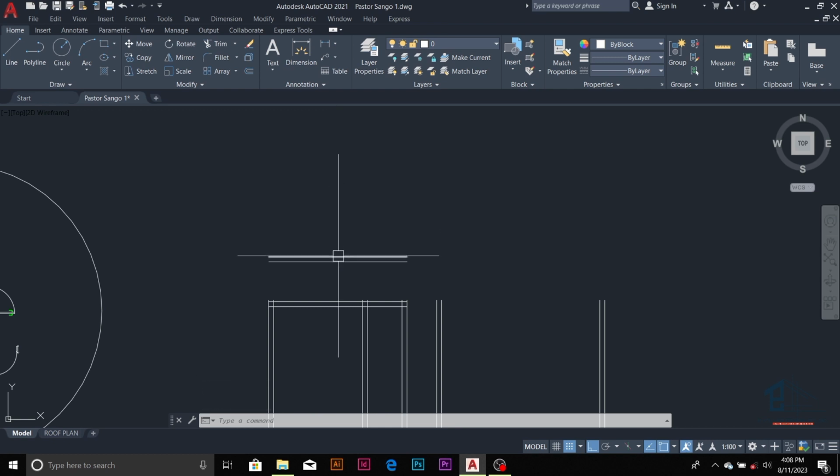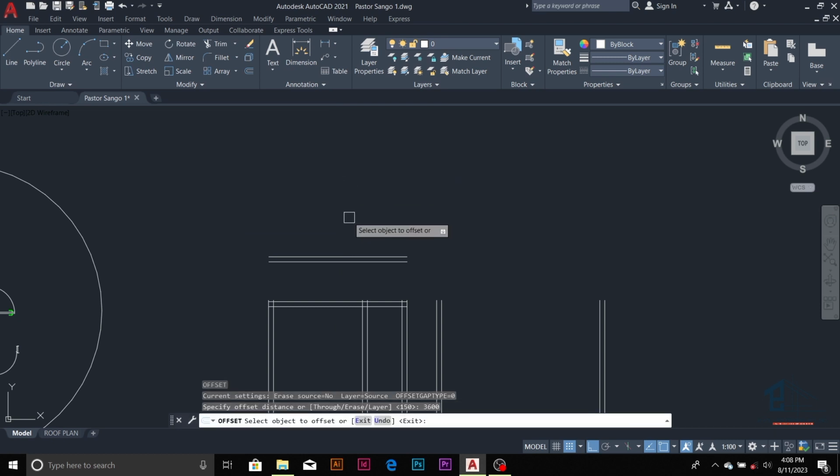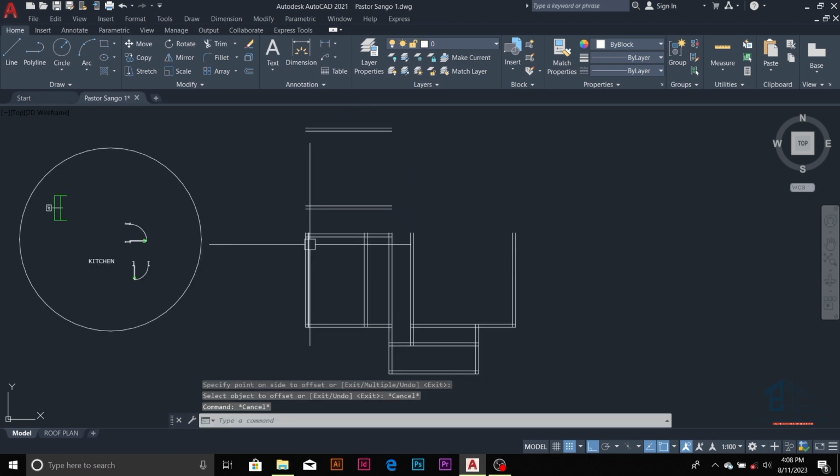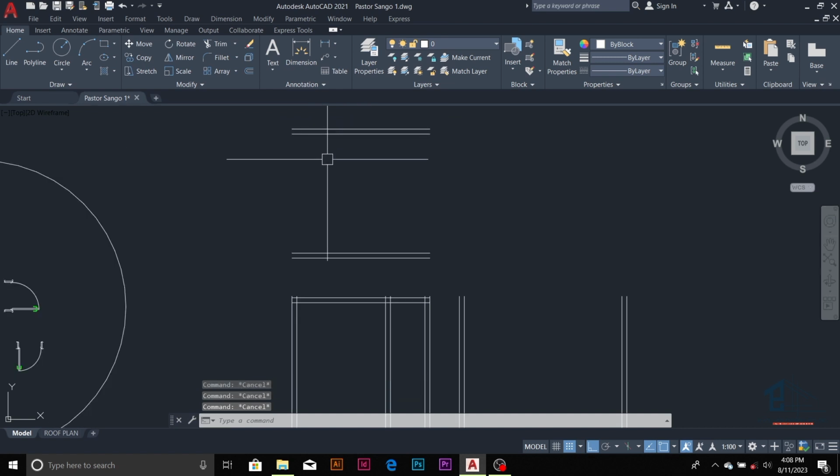So from this side to this side, I'm measuring 3.6, offset 3.6. Block wall, offset 150. So I want this one to go and meet this one. I told you in our last video that the solution for that is using fillets. All we have taught in that last video, you are just going to be making use of it in reality here.